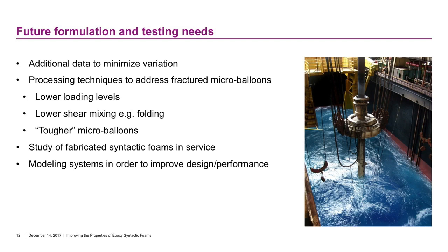Processing techniques now come strongly into play because we experienced some microballoon fracturing and as a result some inconsistent property measurement. So examining lower loading levels, different types of mixing techniques, perhaps different types of microballoons with different degrees of toughness, if you will, to prevent and to safeguard against fracture. These are things that we would like to take a closer look at.